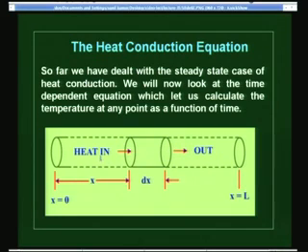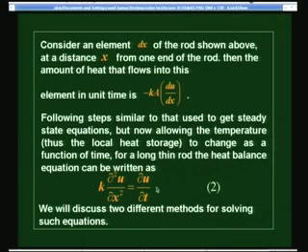So you take any element where the heat that comes in here is qx, and what heat goes out here is q at x plus delta x. So that will be the heat flux into the cross sectional area, which let's take as A. So the heat flux, let's take it as q here, and then q of x, and then what goes out will be q at x plus delta x, as we saw earlier. Now we know that q is related to the gradient of temperature, that is del u by del x in this particular case. So these equations would lead to something like this.